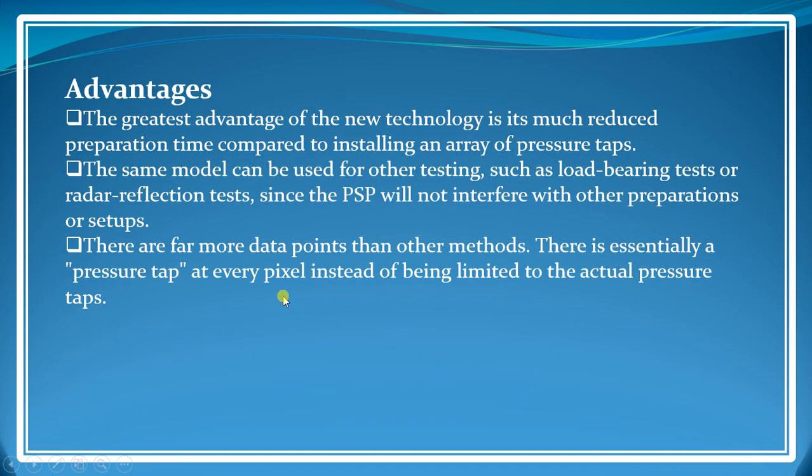Now what are the advantages of PSPs? The greatest advantage of this new technology is its much reduced preparation time compared to installing an array of pressure taps. As you can understand, it's just paint, so we can spray it or brush it, and you can make a pressure sensitive paint.